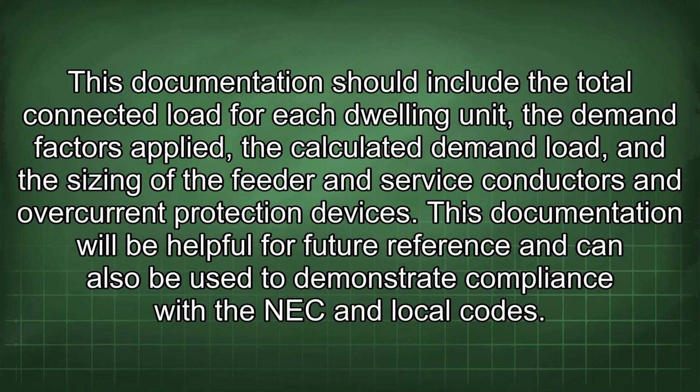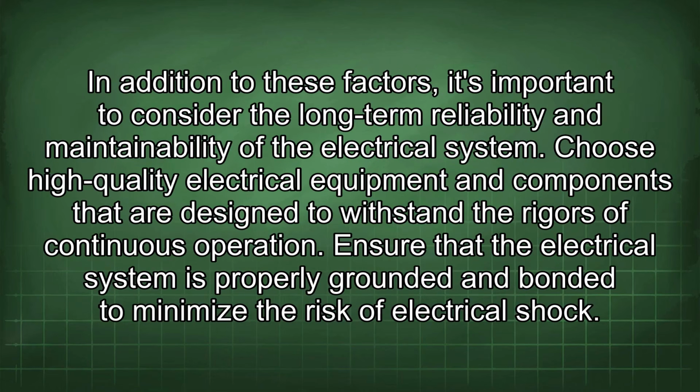This documentation should include the total connected load for each dwelling unit, the demand factors applied, the calculated demand load, and the sizing of the feeder and service conductors and overcurrent protection devices. This documentation will be helpful for future reference and can also be used to demonstrate compliance with the NEC and local codes.